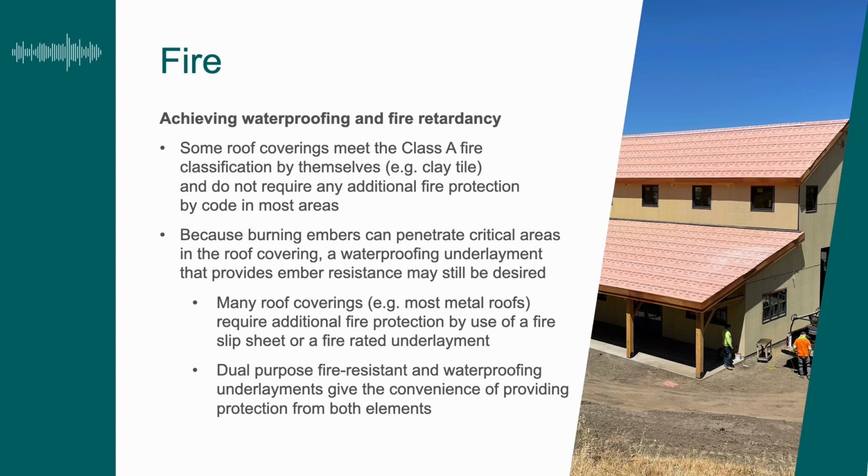Typically, flying embers are more of a problem when hitting the side of the house, up underneath the eave, that type of thing. But fire ratings are still required on all roof coverings that we do, and having underlayments as part of that assembly is a requirement. Okay?